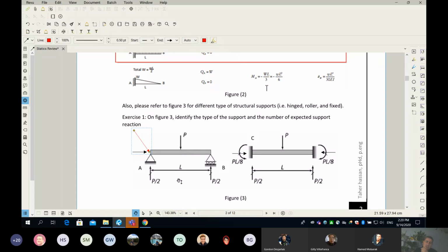Thank you so much. Yes, this is a hinge, okay? And before I go to other support, let's watch what's happening here. So this support here, it's simply a restraint. Support means restrain. It restrains this point of the structure from movement in two directions, which is the Y direction and X direction. We call it hinge, like the hinge of your door.